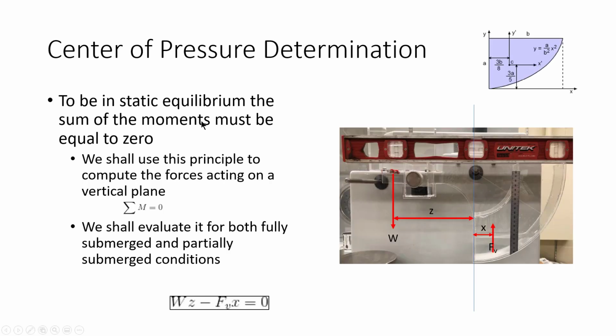So in today's lab, we will use a hydrostatic bench apparatus to calculate our forces. Essentially what we have is a pivot point here, and a planar surface right here, and we want to know what force this column of water exerts on that planar surface.